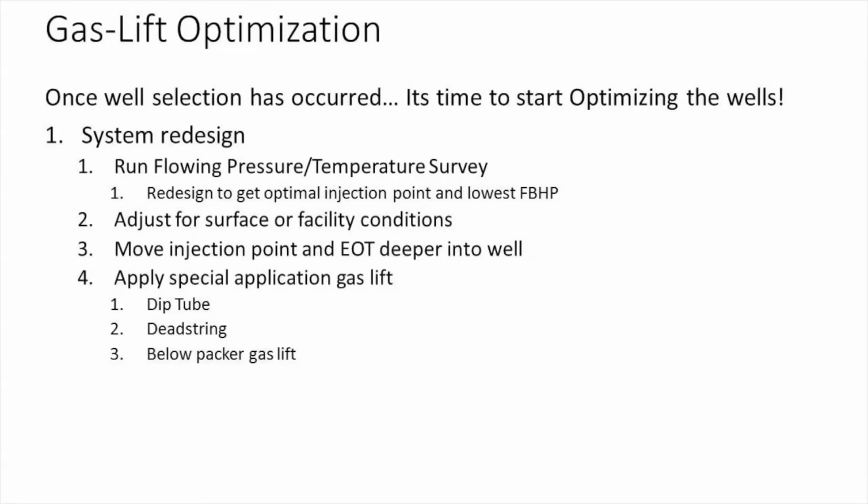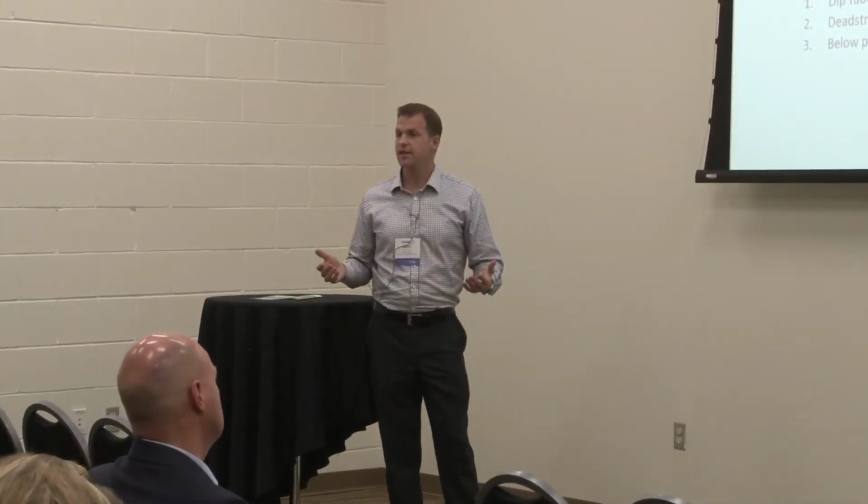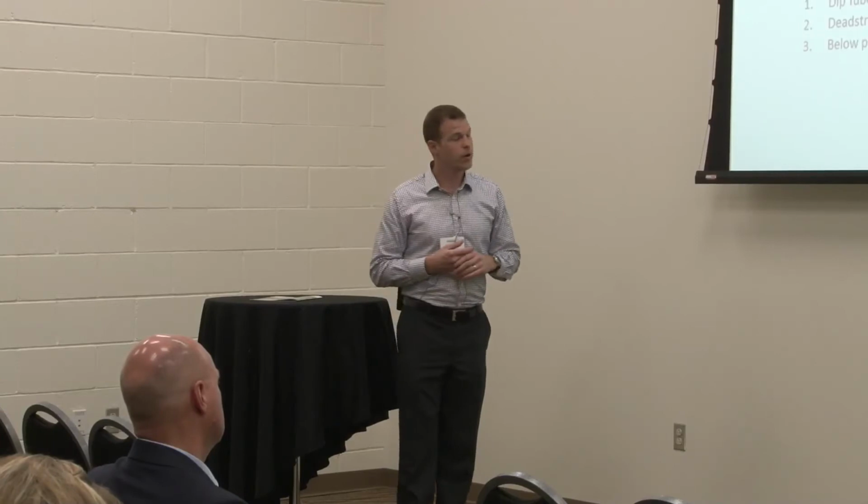So, system redesigns. System redesign typically requires a workover or a wireline rig. So it's typically a last resort means to optimize a well, mostly because this one costs the most money compared to adjustments in injection gas or facility changes. But typically they can increase production, and they can extend the life of the well based off of the parameters.